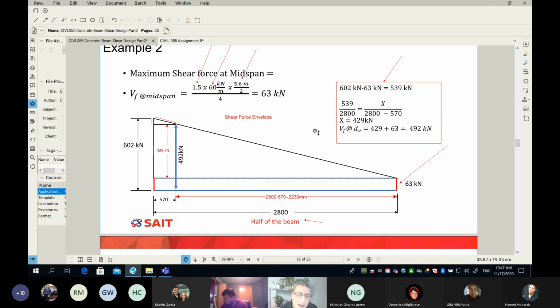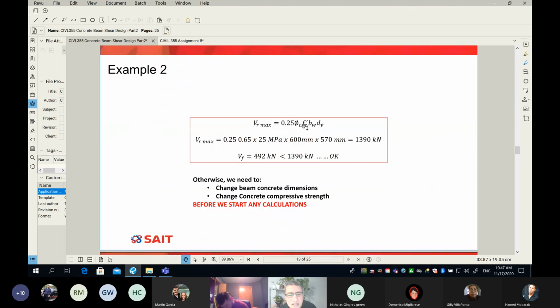Because a diagram corresponds to one load configuration, and if the load configuration changes, then maybe we can exceed the value on a diagram. But the envelope, which is simply the maximum, means there's no way for the force to exceed the values in the diagram you can see. Okay, if everybody follows, then we can proceed to the next step.